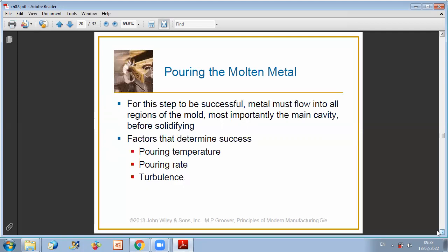The more complex the geometry of your final product, the more challenging this is, and you should design a convenient riser in order to allow molten metal to reach all extreme parts without blocking effects.